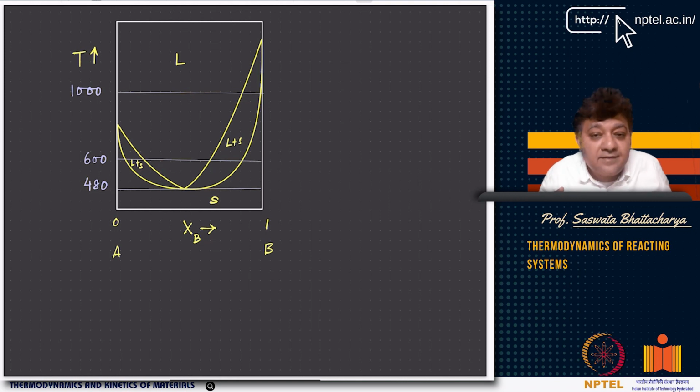This type of phase diagram you will see is only possible when you have the liquid and solid caving into a single point. It can also happen on the upward side, right? This is possible only when one of the phases, liquid or solid, has to be taken as a regular solution. If both are ideal solutions, you basically get a lens-type diagram, like the type 2 phase diagram, right?